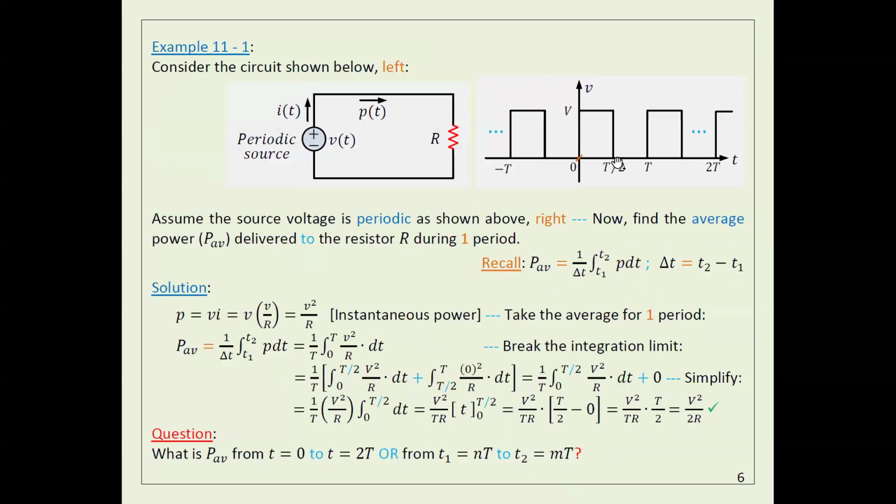So here in this example, you can see a voltage, and here I connected it to a resistance. The power here equals V times I, and I is V divided by R. So I can say the power is V squared divided by R. This is the instantaneous power, in case R here is just a resistance.